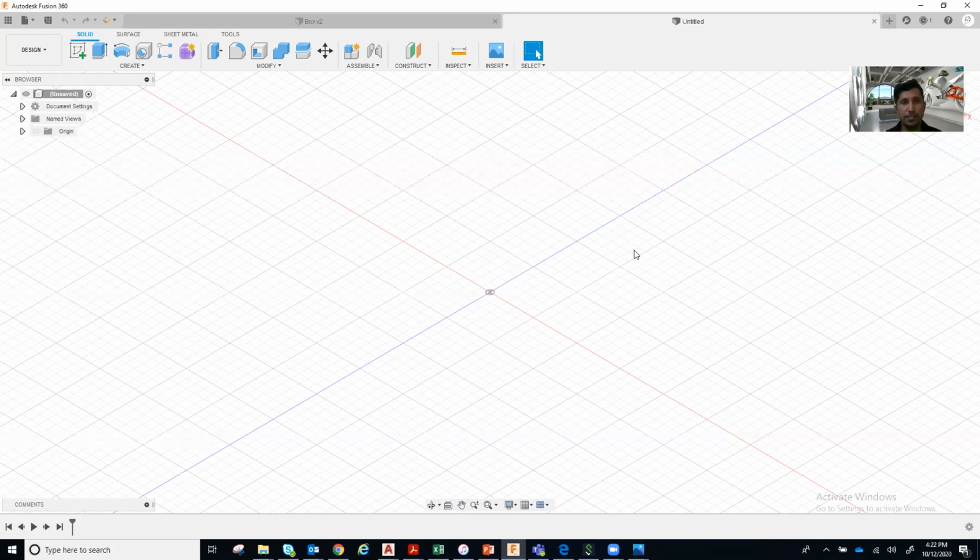My next project is the same laptop, everything is the same, but it should be 15-inch. So rather than designing everything new, if I change the screen size from 13-inch to 15-inch, everything should automatically get updated. Something like that, we call it parametric design.